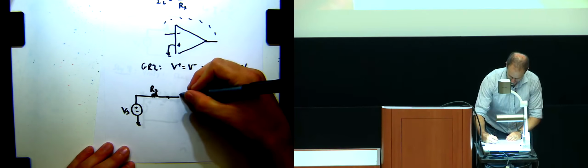Yeah, exactly. So remember, the other golden rule was that I plus equals I minus equals 0, which you said as the op-amp looks like an open circuit. Both of those statements are equivalent, right? So that means that this current here is indeed 0. So if there's no current flowing here, the only place this current can flow is through there, right? Okay. And indeed, that is exactly the property that we're going to rely on. All right, so from the design problem, we're quote-unquote done.